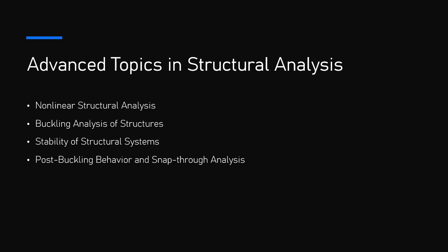3. Applications of snap-through. Aerospace and space structures. In inflatable space structures, the snap-through behavior must be analyzed to ensure that the structure does not collapse or shift configuration unexpectedly. Civil engineering. In temporary or lightweight structures, such as tents or membranes, snap-through behavior is a key consideration in design. The structure must be able to handle large deformations without loss of integrity.